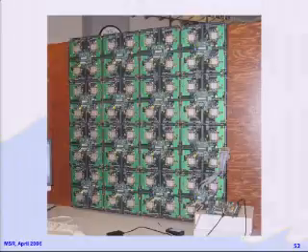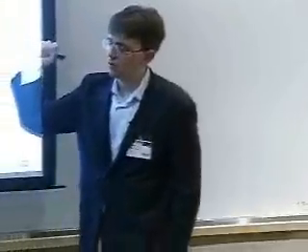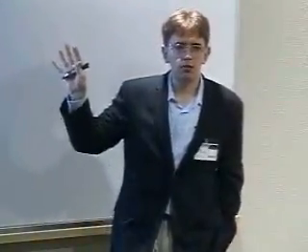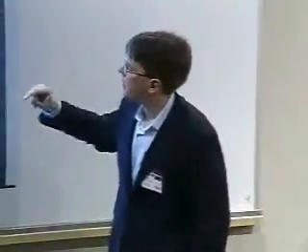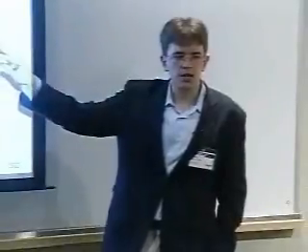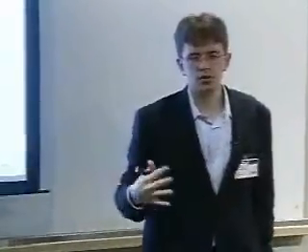The most interesting aspect of that is this new hardware simulation, or hardware prototyping system that we've built. This is an array of 64 FPGAs. It's about 4 feet on a side. And what we're going to use this for is taking our RTL model and mapping it onto these FPGAs so that we can run larger systems and do larger system-level work.